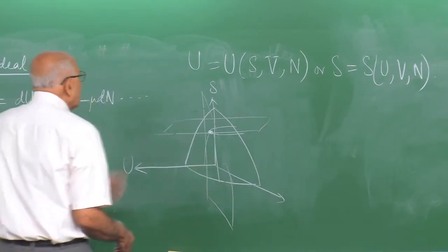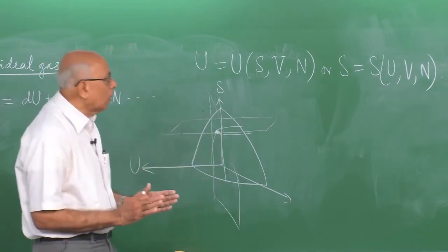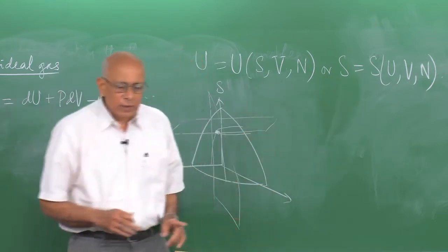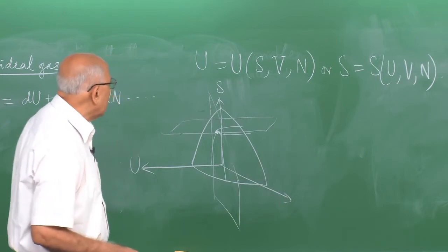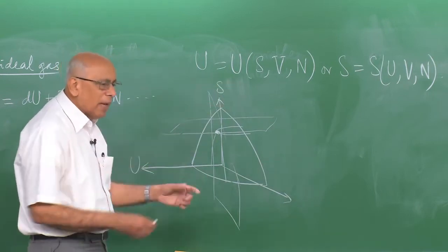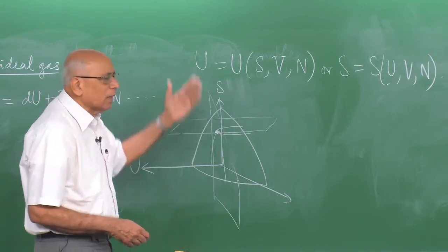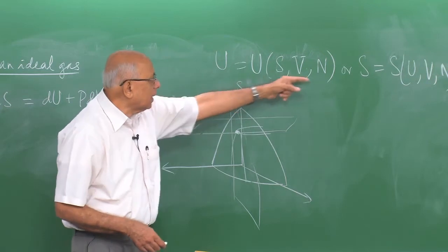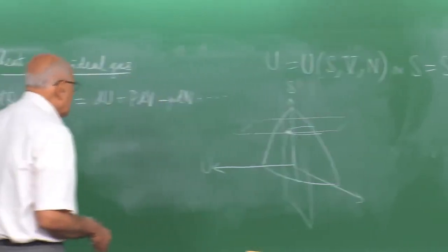But the idea is that thermal equilibrium corresponds to the minimum, or in the case of the entropy, a maximum of a certain thermodynamic potential or state function, if you like. Energy is easy to understand because in mechanical equilibrium, the energy is minimized, so it is convenient to say that the internal energy is a minimum in the case where U is a function of S, V, N and the other fluxes in this problem. Okay.